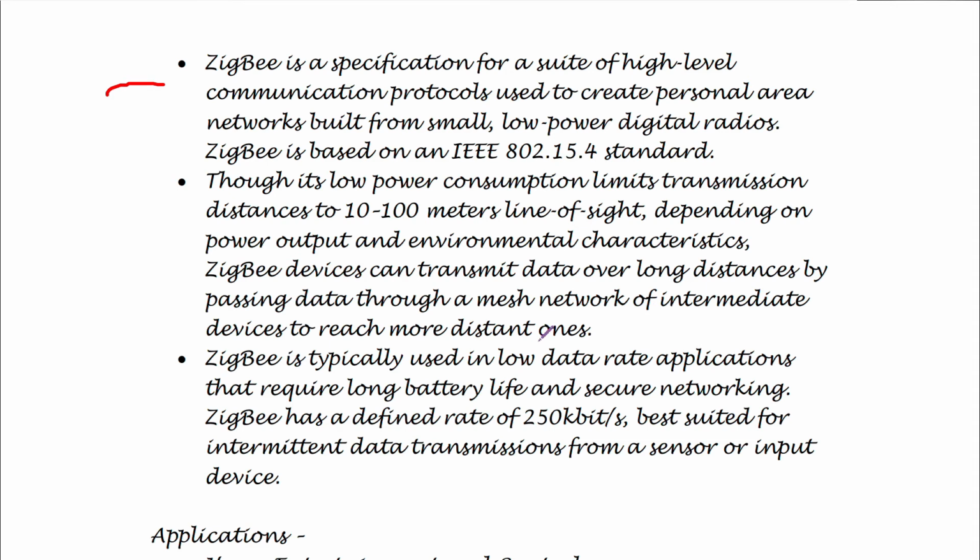So Zigbee is low power and it actually has a short range. It does not have a very huge range, but we can create a mesh network using Zigbee, meaning we can attach multiple Zigbee devices together at a specific range for communicating from this point to this point, right? So these Zigbee devices will obviously be in the operating range of around 10 to 100 meters, but say this distance is quite long. So using this mesh network technique, we can communicate from this device to this device.